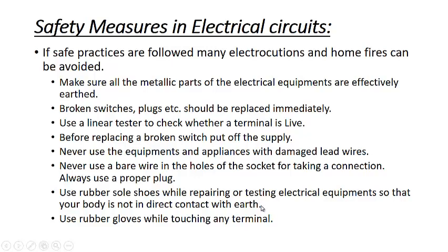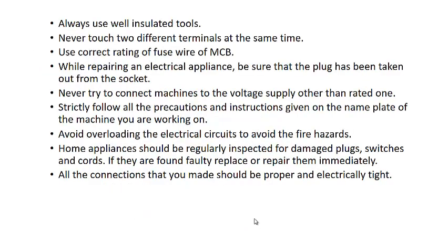You may sometimes use some wooden shoes as well, or some wood piece that's placed under your feet where you are testing or repairing some electrical equipment. Use rubber gloves while touching any terminal, because even if the terminal is at some potential or has some live voltage, you may be saved from that.